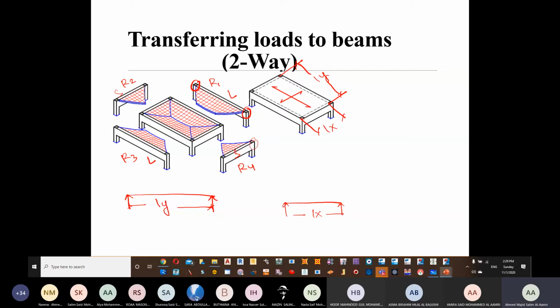And once again, there is a column here, and a column there. Now, after we check the behavior, we said that there will be trapezoidals and triangles. You can see the long beam is taking the trapezoidal, so we have a trapezoidal here, and then the short beam is taking a triangle. If you remember, when we took the yield lines, the long one takes a trapezoidal and the short one takes a triangle. This is what you have studied for a long time already.